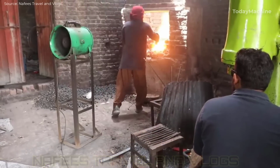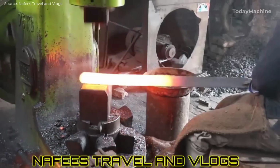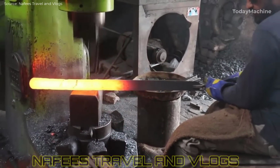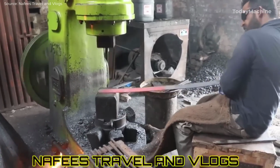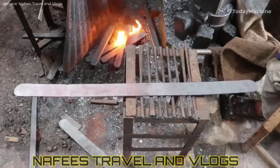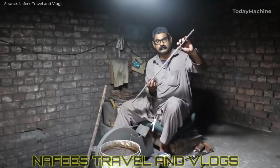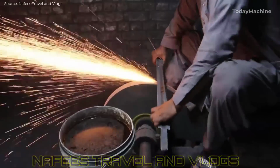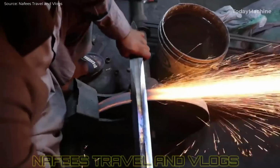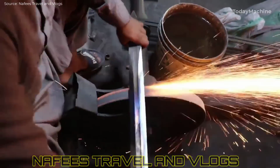Swordsmiths use a variety of hammers, anvils, and tongs to meticulously shape the blade. The forging process can take several days, depending on the complexity of the sword's design. After the initial shaping, the blade is subjected to repeated cycles of heating and hammering, followed by careful cooling, to enhance its strength and flexibility. This process, known as tempering, ensures that the blade can withstand the rigors of combat while maintaining a sharp edge.